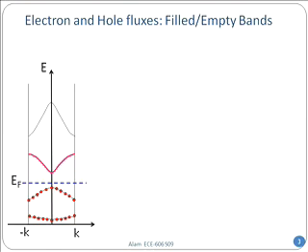The current associated with the purple band, we are calling J3, because it's the third band from the bottom. All the electrons should have a minus q, and I must sum over all the velocities, because charge multiplied by velocity gives me the current. But here, I don't have any electrons, so of course I do not have any current, because there's nothing here to carry the current. So I have it 0.